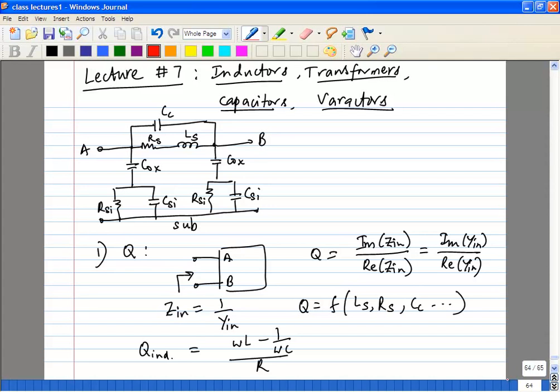Exactly, you can't say without analyzing what the distances are, without really running the electromagnetic tool. It is not that intuitive. It depends on the actual distances from the substrate as well as the actual resistivities of your metal lines. Is that clear?